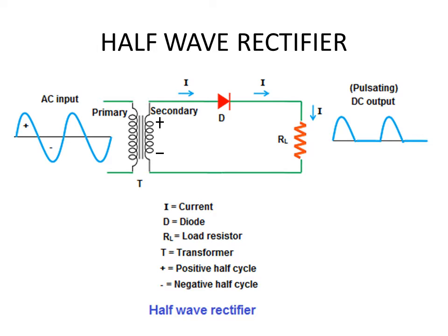So some voltage will be present only during the positive cycle, and even then the voltage will be varying because the input is varying. Using the half wave rectifier, we have successfully made DC output voltage from AC voltage.